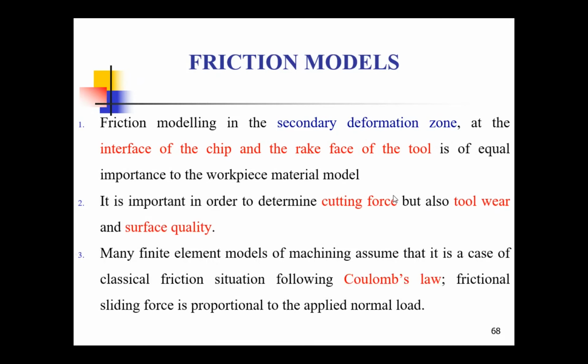So it all depends on the friction models that we will be using. The friction model that we will be using in the standard packages is the Coulomb law, that is mu is equal to F by N. So initially itself we have seen that the friction coefficient is constant. We have assumed that friction coefficient mu is constant. But normally in experimental turning process, the friction coefficient will not be constant, but we have to assume it as constant.